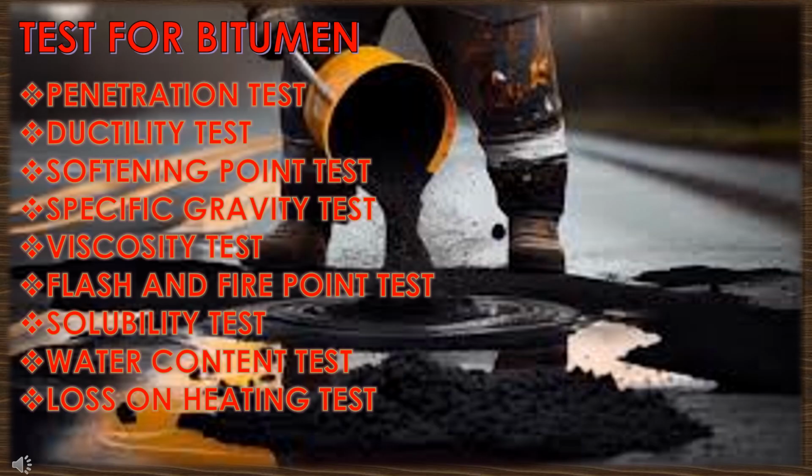Let's start with the tests for bitumen. There are mainly 9 tests for bitumen: penetration test, ductility test, softening point test, specific gravity test, viscosity test, flash and fire point test, solubility test, water content test, and loss on heating test. So, let's start with the penetration test.